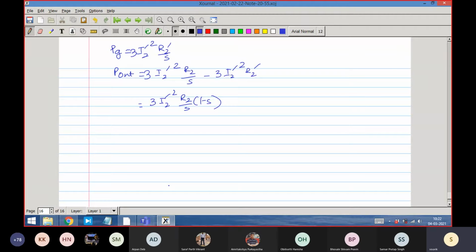This is the power out, right? Here I should pause a little bit. This power output is slightly internal, because after this there is some loss. Because it is a mechanical system, it will have some loss of friction, windage, etc. Some mechanical loss will be coming before it goes to the shaft. Shaft power is the power that is useful for the mechanical system. So it is still an internal power. We have just subtracted the rotor copper loss. This corresponds to the rotor copper loss. Still it is a bit internal.